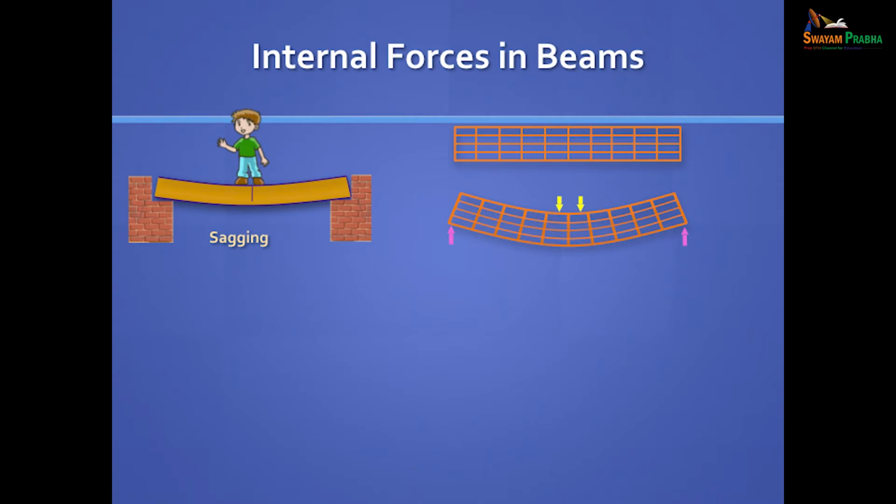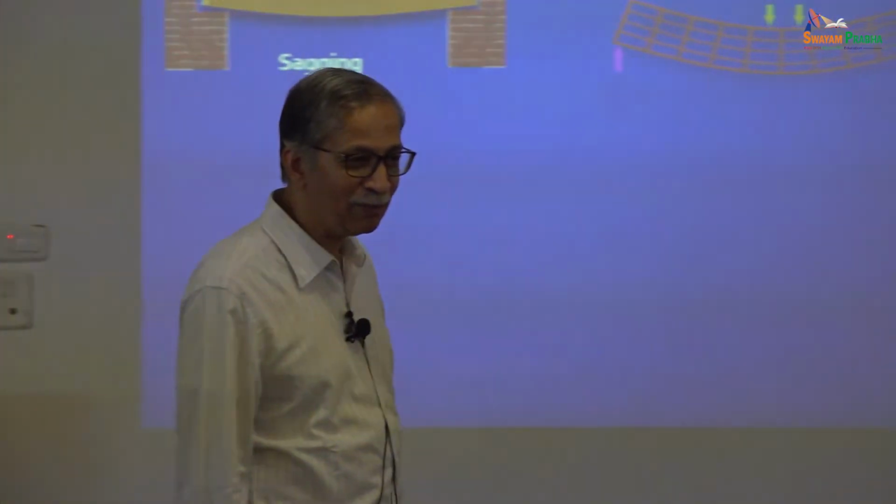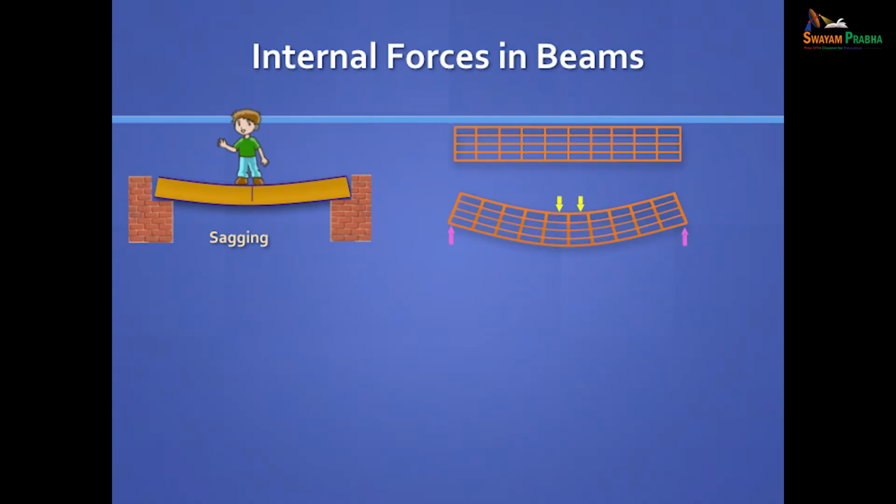And you see what's happened to the straight lines, the vertical lines and the horizontal lines. Okay? Vertical lines, what do you see? Ideally, everywhere. Will they be straight or will they be inclined? What's your view? In other words, will there be any warping? Well, there will be. We'll look at that a little later. But if I cut a section here, in this region there's no bending shear. That's pure bending. So in this region it's clean and there's no shear.